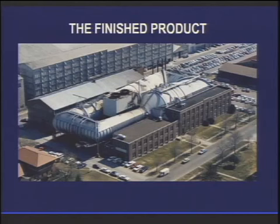A couple little things about this. Although the tunnel was supposedly designed for Mach 1.15, if you hold your mouth right and the wind's blowing from the right direction, you can actually squeeze it up to 1.2. But the test section was designed for 1.3. So you should be able to increase the Mach number to 1.3 without doing any modifications to the test section, say by adding auxiliary suction or something like that.